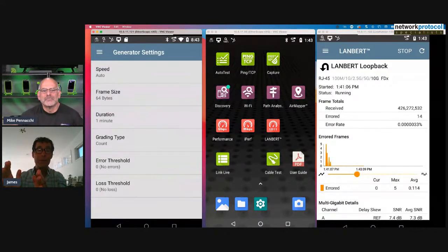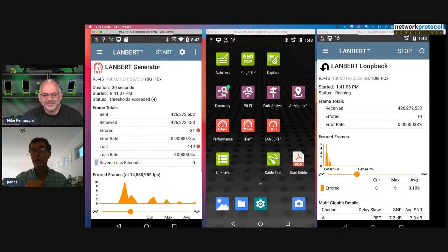And then when the IEEE hit the brakes, what they said is, okay, we know this PAM16 coding is working pretty good. 10 gigabit wired Ethernet had been around for 5-6 years and was performing well. What if we just slow it down and keep the same levels but cut the clock speed in half, right? And so that's where they brought the clock speed down to operate within the bandwidth of the cable. And that's basically how they achieved 2.5 gig rates over media that didn't have the same frequency characteristics.